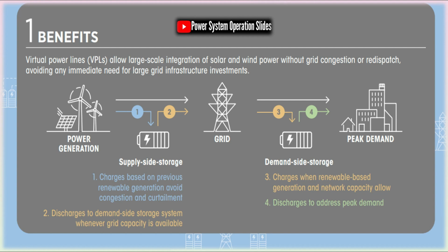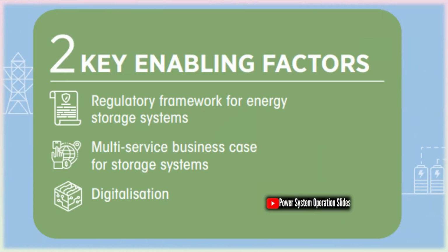Key components, the building blocks: Wide area measurement system (WAMS), PMUs (phasor measurement units) and fast telemetry to measure voltages, angles, frequencies, and flows in real time. Energy management system and distribution management system (EMS/DMS) and an optimization layer that runs state estimation and flow optimization.